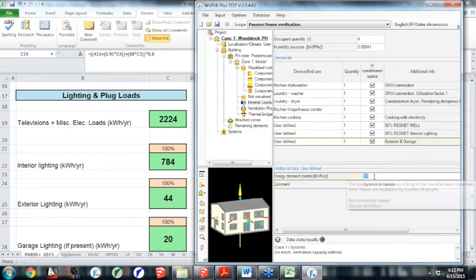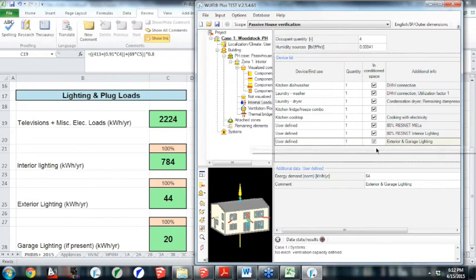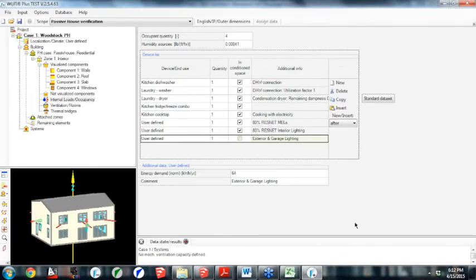One important thing is that this exterior lighting is not inside the envelope, so I'm going to uncheck in conditioned space so that it doesn't calculate within the internal gains. So that's a short workaround that will be eliminated again in a couple weeks, but this is how you calculate the lighting and plug loads. This is pretty much it for the inner loads and occupancy with a single zone residential project. So I'm going to move on from this.